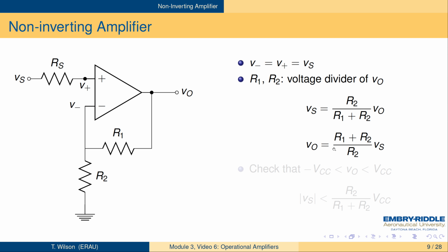And the gain is going to be entirely determined, even though there's a huge gain in here of 100,000, the actual gain is going to be determined entirely by what we hook up to it. It's a great little device, that's why it's called an operational amplifier. That's the operational part of it. It just lets you do things with it in a very convenient way by what you hook up externally, regardless of the fact that it's got this huge gain and the voltage here is very small and all that kind of stuff. It's a great little box. It supplies enough current.